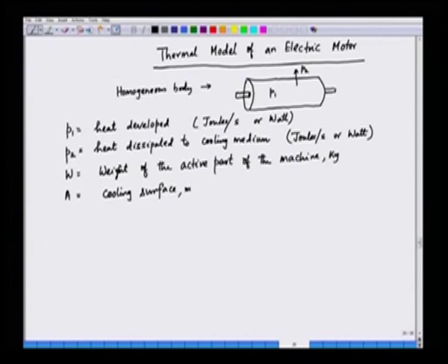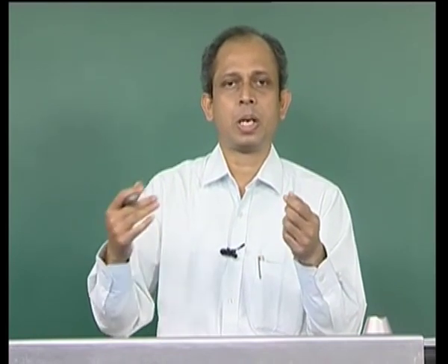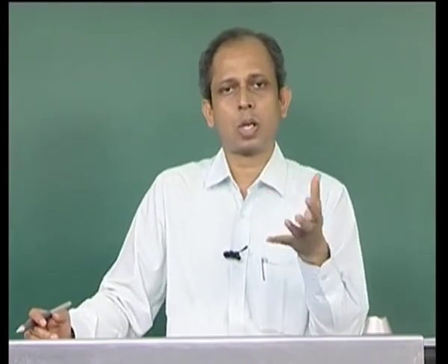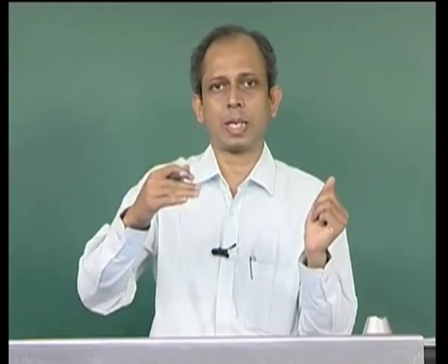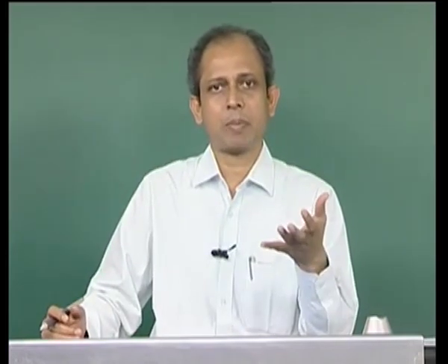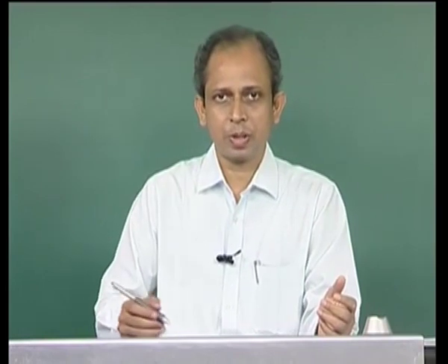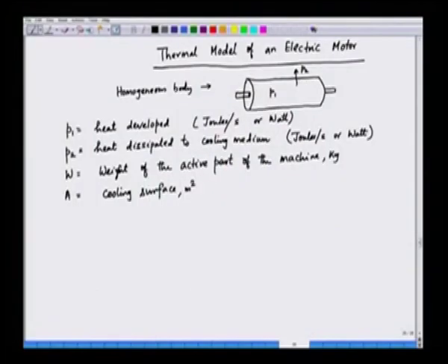in meter square. So, the motor has got some surface area. The surface area is primarily for cooling. Now, we must have seen that in an induction motor or in many motors, the surface of the motor is not quite smooth, it is basically corrugated. The surface is corrugated primarily to increase the cooling area. If the area is more, the cooling will be more effective. So, in this example, this is basically the surface from which the heat is coming out, and this is having an area that is A.